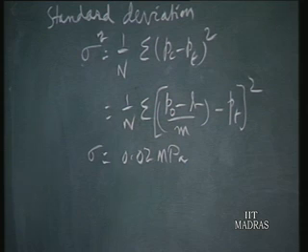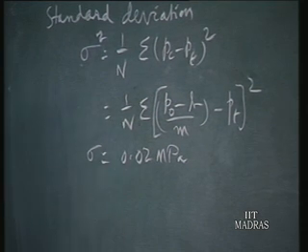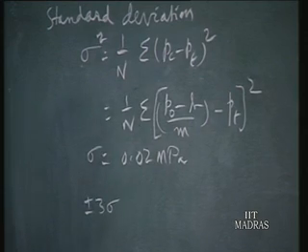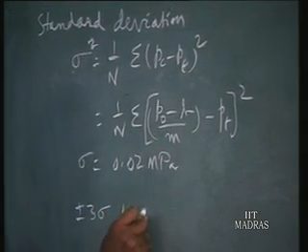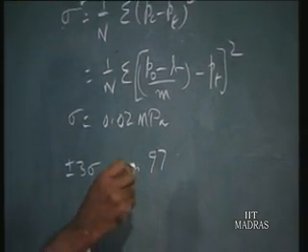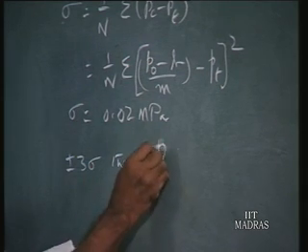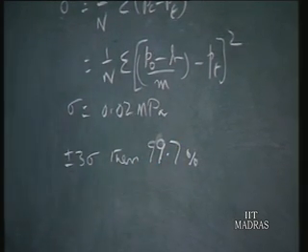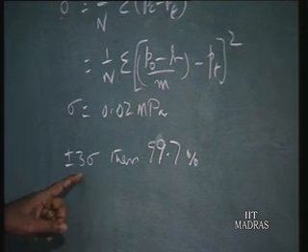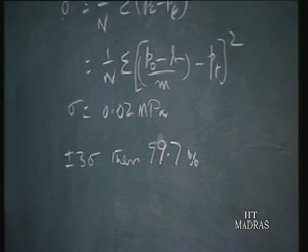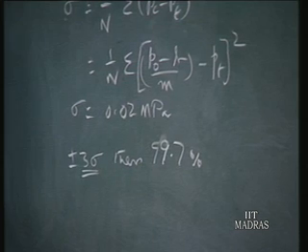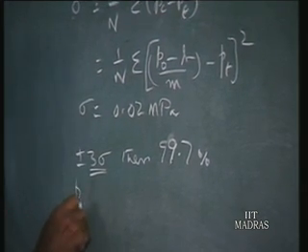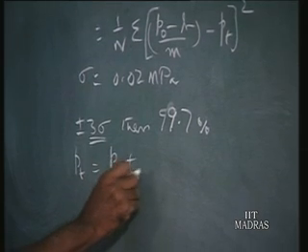By Gaussian distribution, if we take the limit as plus or minus 3 sigma, then 99.7% of the readings will have error within the plus or minus 3 sigma limit. So this is normally adopted. The error will be put as plus or minus 3 sigma. So now pt is equal to pc plus or minus 3 sigma.